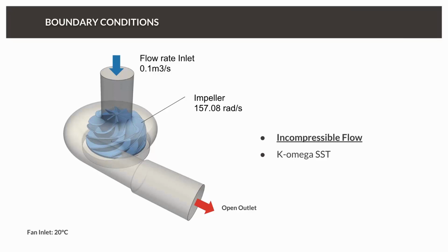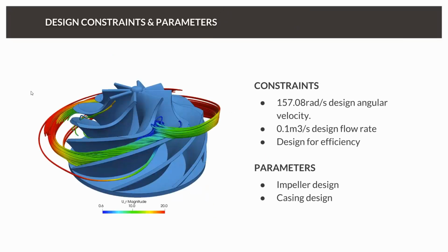Therefore, one of the first things we have to do is to actually extract the fluid region. And this is something we do in our CAD system. You can also do it in theory on SimScale, but usually in your own CAD system it's much more comfortable. Once we have prepared that model, the next step is to mesh it, so to divide it into a finite number of cells. This step is very important because there we are defining which local accuracy some later simulation will have. And now I would suggest let's switch to the SimScale platform and take a look at the simulation project itself.